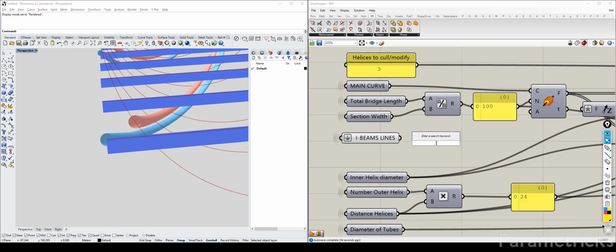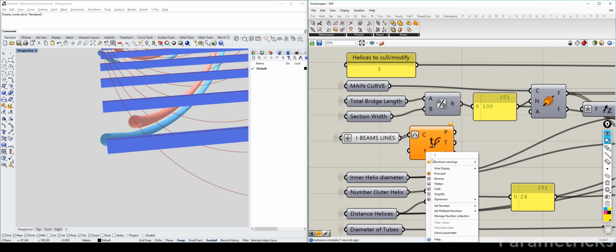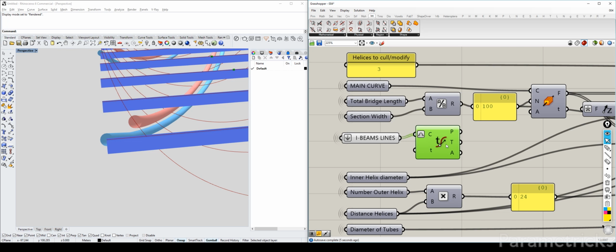and enable that. And let's try to get the center point, CRV evaluation. From this one, reparameterize so that we can insert 0.5 as the middle point, rather than knowing the length of this and then dividing that length by 2. So this is an easy way for us to get a middle point of that.